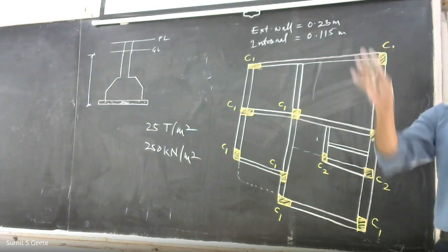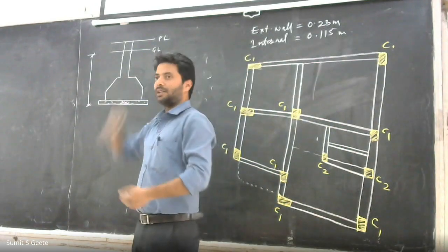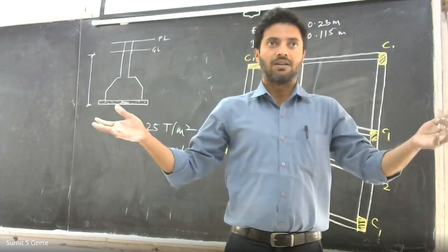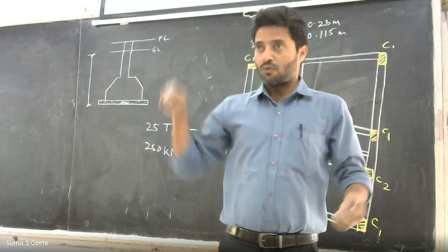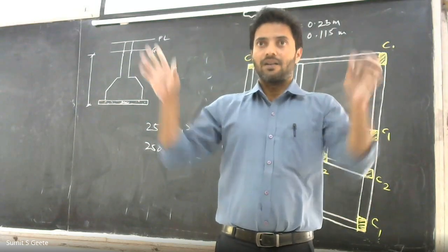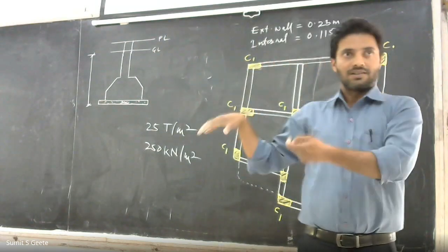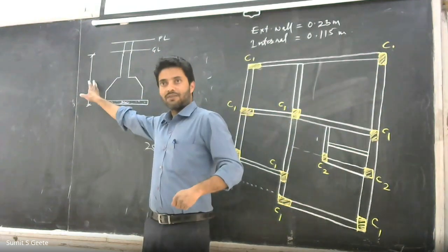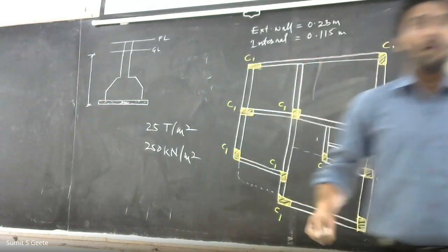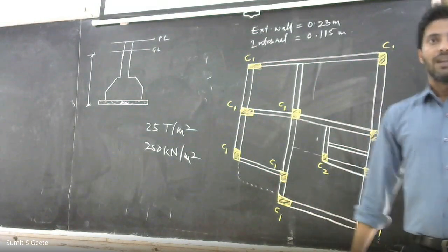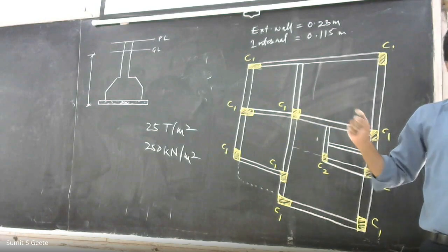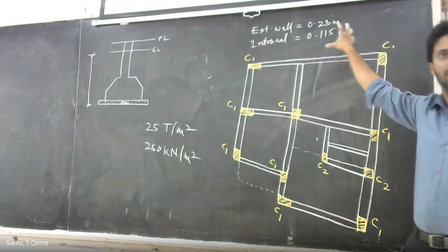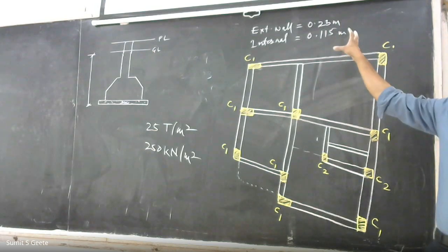If they clearly define that depth of excavation is say 1.5 meter, then what happens? Whether at 1.5 meter you are getting that SBC or not is a question mark. So to save themselves, the structural designer writes that the depth of excavation is up to that level at which you are getting that particular SBC. And in structural design, SBC is clearly mentioned at the top corner, children. Right top corner. Is it okay?